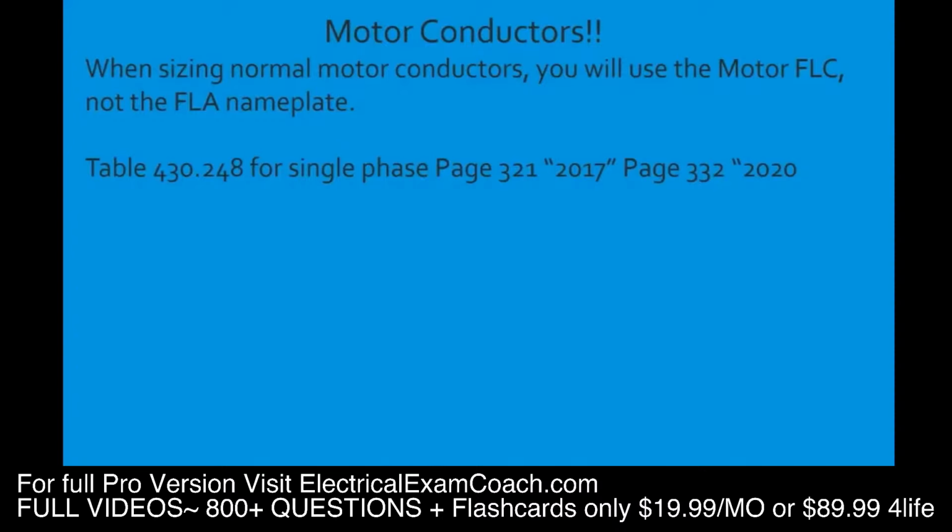Now continuing to read the table from top to bottom, left to right, using the black bold headings to navigate the table, we're going to start on the left-hand side. If you notice there, you have your horsepower. That's going to be whatever the horsepower of the motor is. Now across the top, all of those black bold headings are respective voltages. So what you do is you go to your horsepower, and then you come over and you tee off with whatever voltage your motor or your question states.